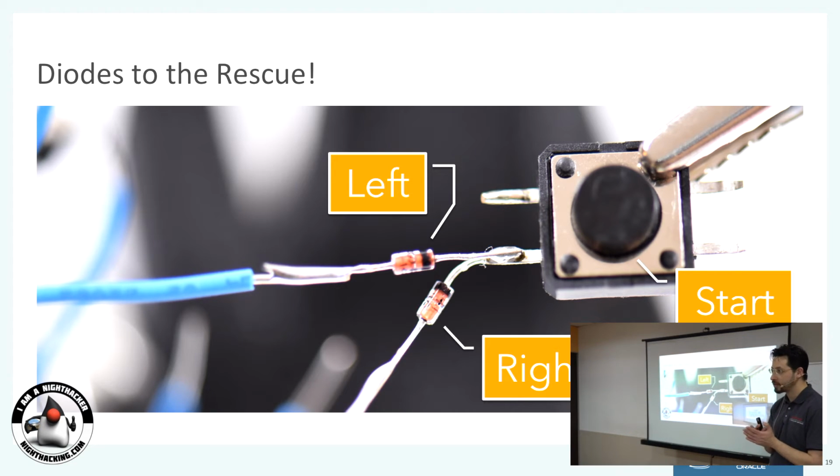So this works great, except in one case. Can anyone think of the failure case where this doesn't actually work? Yeah, okay. So if you press start and left, for example, at the same time, that would register as start. Same thing, like if you press select and up, it would register as select, not up. So fortunately, most games don't require that you jam start and up or select and up at the same time, right? It's an uncommon gesture. Except my buddy who did the emulator pointed out that there's one game, Mike Tyson's Punch-Out, where for the smash moves, you have to press, I think, select or start and an arrow key at the same time. So I broke one game. But I think it's a reasonable trade-off. It works most of the time. And you can see it works quite well for 99% of the games.